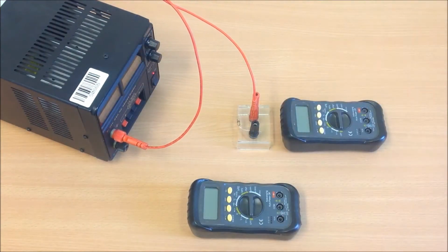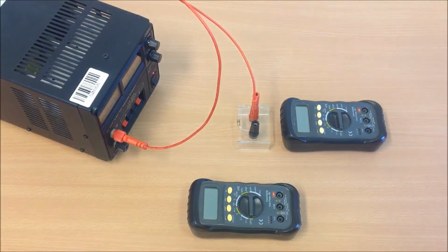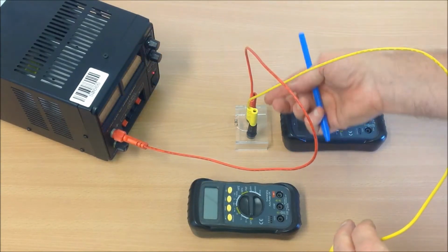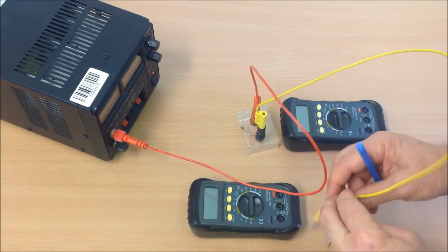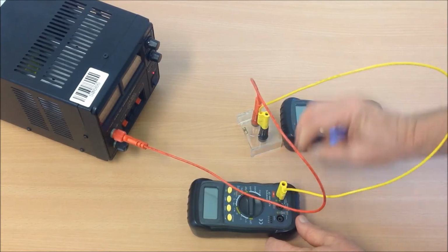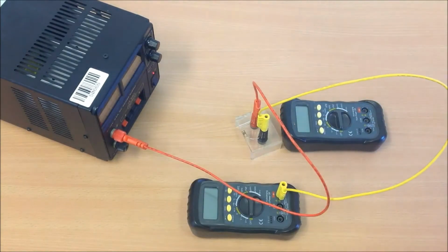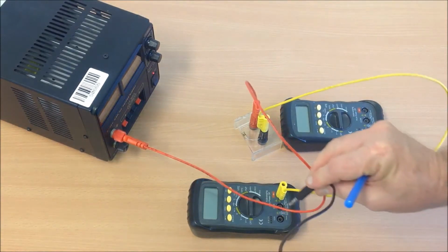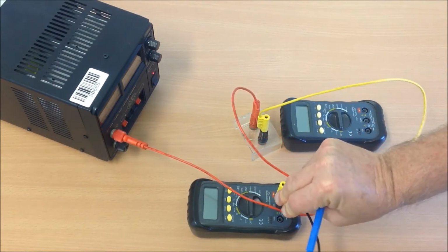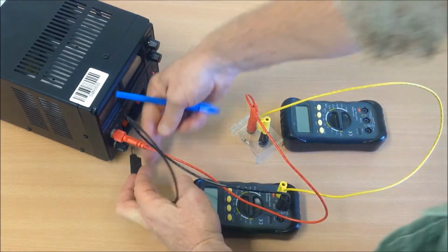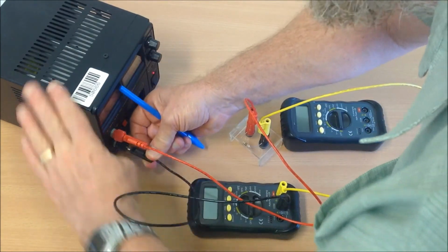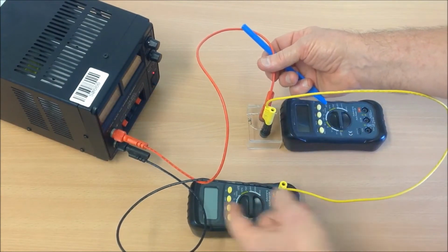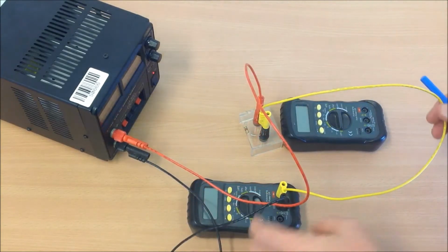We then need to connect from the resistor to the current meter, and since I'm going from the positive side of the power supply through the resistor, I'm going to go to the positive side of the meter because I'm coming down from positive towards negative, and then finally I'll connect back from that meter through the common input back to the power supply. And that basic circuit provides the current that flows through the resistor, through the meter and back to the power supply.